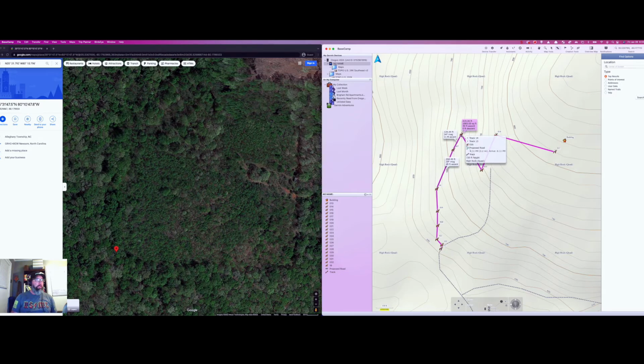Now, if you do the math on there, it's not hard to figure it out. If you say 39 feet divided by 419 feet, you've got basically a 9.3% slope. So that gives you a percentage of slope that you have over that 419 feet.